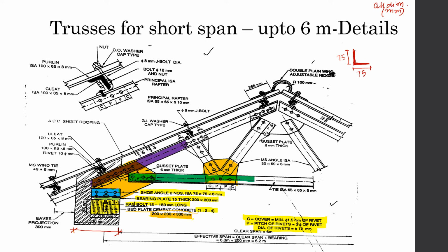So here for a short span truss, at 1/3 distance of the whole span, from support till the 1/3 length of the span, the first node is provided where they place a gusset plate with which they fix struts. The struts are the intermediate members which are under force.